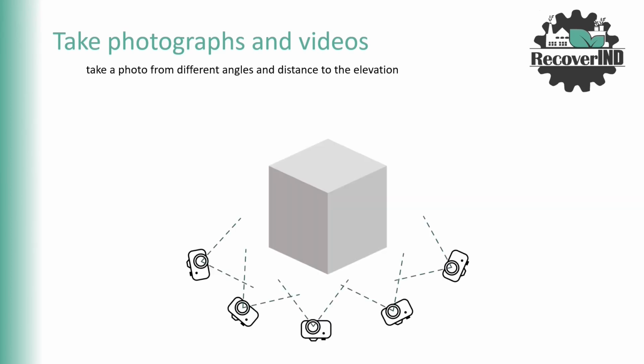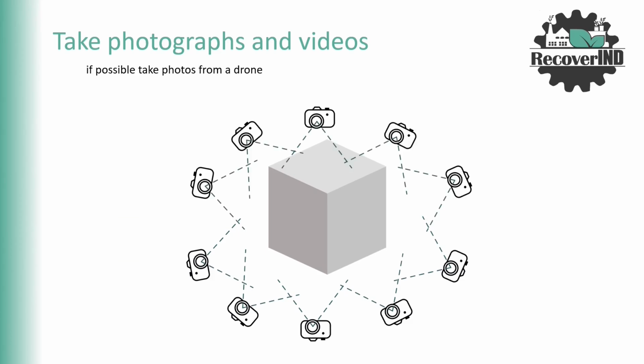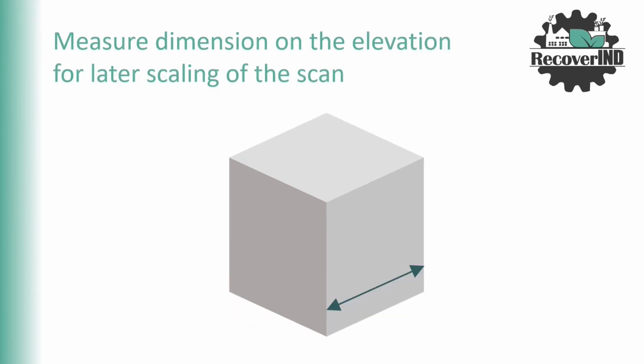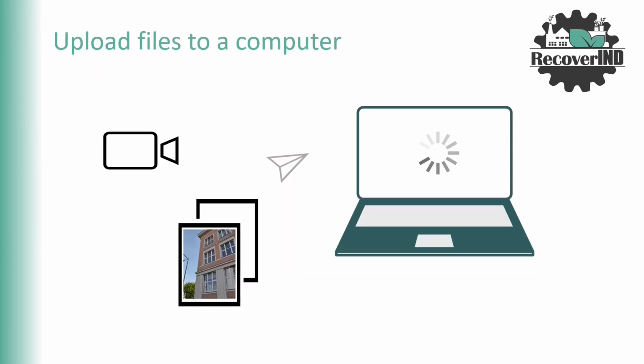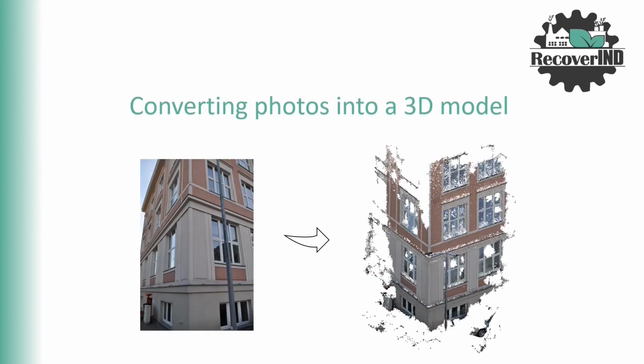Take a photo from different angles and distance to the elevation. If possible, take photos from a drone. Measure dimension on the elevation for later scaling of the scan. Upload files to a computer.